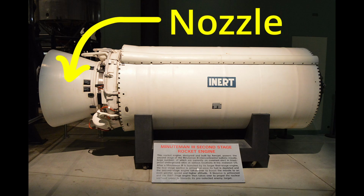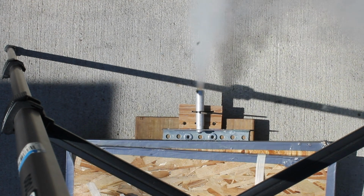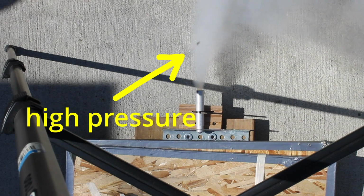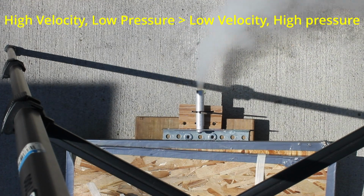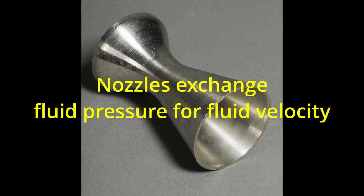Nozzles are needed for making a rocket engine, well, not suck. In the footage from the first test, we can see that the exhaust velocity is pretty low, but the pressure is fairly high. What we want is the opposite, high velocity exhaust at a low pressure, as this will create the maximum thrust. This is exactly what a nozzle does, thankfully, exchanging pressure for velocity.